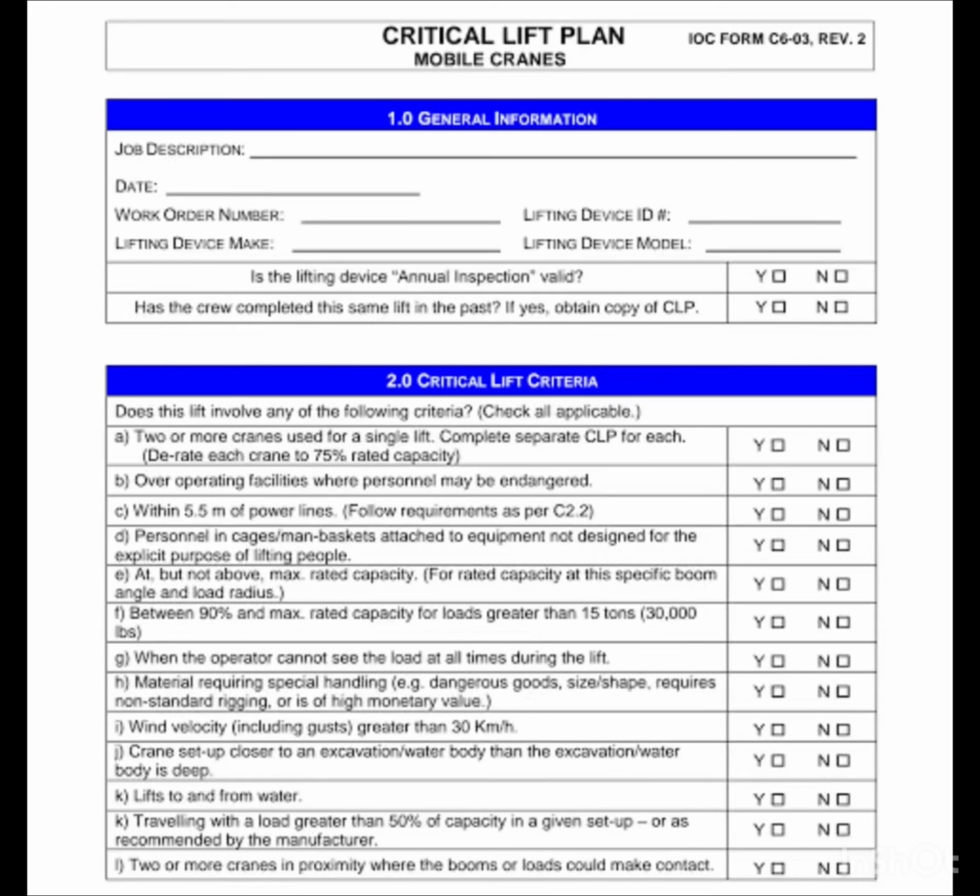In what condition is a critical lift plan required? High load weight, when the load weight is close to or exceeds 75% of the crane's rated capacity, or during tandem lifts.